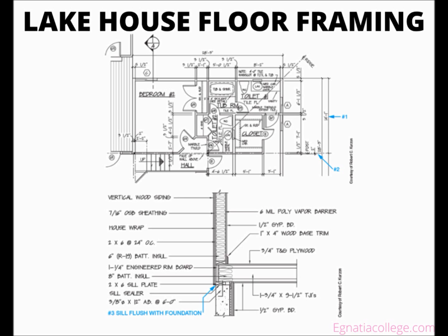The inner ends of the remaining floor joists in the lake house are supported by bearing walls in the lower level. For example, some of the kitchen floor joists are supported by the west wall of the playroom near the fireplace, and some by the LVL beam that spans the distance from the playroom wall to the foundation in the crawl space. The size and spacing of material to be used are given on the framing plan by a note.